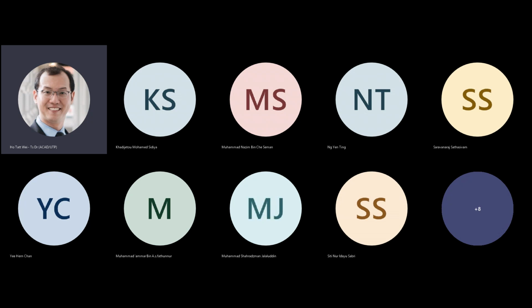So this is just one parallel multiplexer, but you can also implement a multiplexer as something like this, a cascaded set of multiplexers. And if you use the pass transistor to cascade it that way, after 4, 5, 6 layers, the voltage drop across the logic can actually start to add up. So if you have only 1.1 volt, and you're dropping maybe 0.1 volt here, after four in series, you would actually lose 0.4 volts and your voltage headroom isn't so great anymore. Whereas if you're using something like this, that headroom is a little bit better preserved.